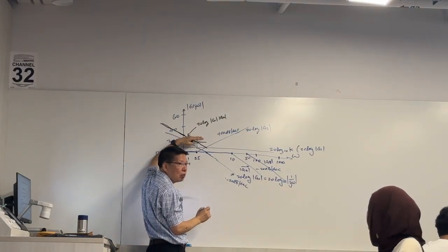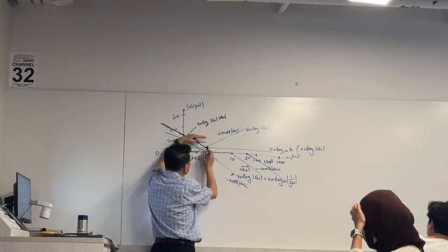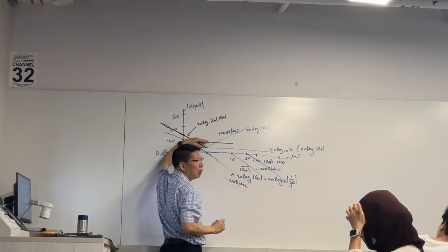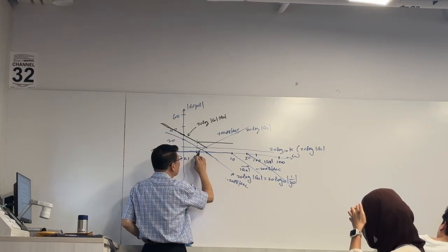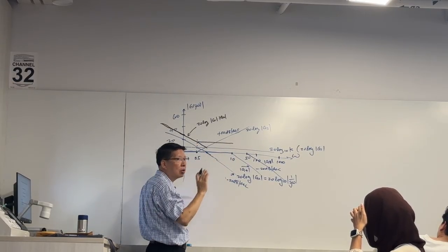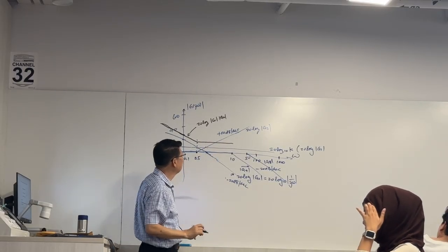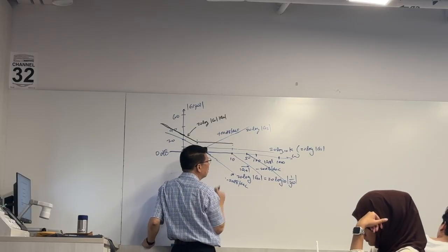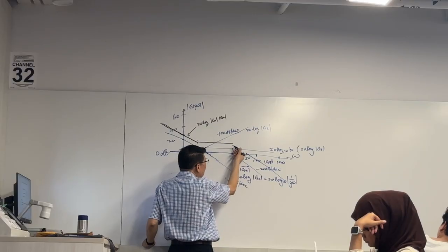So you bend it upwards and then you get 0 dB per decade. This will continue all the way to this 10, where you get a new contribution, because before this, we have only 3 contributions. So that's what you get. At this 10, you get a new contribution, minus 20 dB per decade. So you add to this 0, and then you bend downwards.